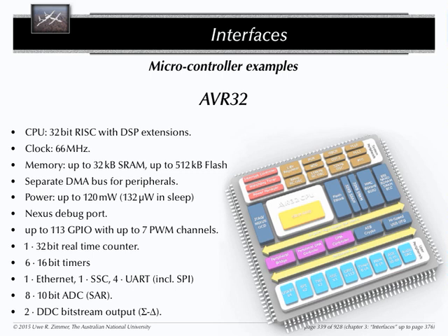As far as I know, the fight was decided, I think, for the USB gang. So the USB interface on the Raspberry Pi has actually the only physical interrupt I/O line which this thing has. Okay. For a real-time course, it's not cutting it. So you need to have other hardware for that. Unfortunately, all the other hardware lends itself much better, and these days you can get, as we will see in a second, hardware which is much easier to handle here.